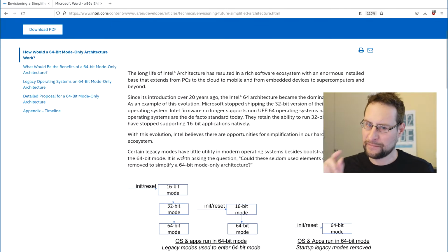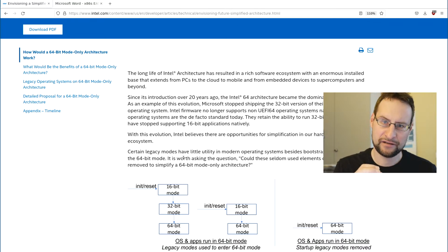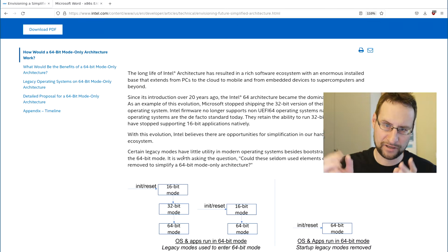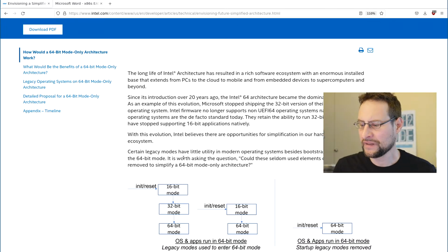So what is this all about? I made a dedicated video, so you probably want to watch that. But the quick summary, the one-minute summary: 8086 had 16-bit execution with 64K segments that were addressed on 16-byte offsets, so you could basically overlap the segments in 16-byte granularity.